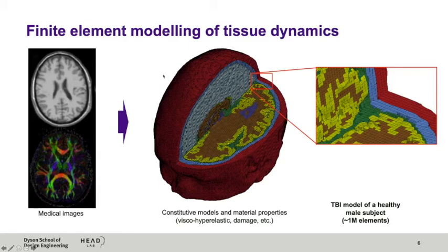And then we represented every voxel of these volumetric images with these cubes. You can see squares here, but in 3D you can imagine it's a cube. These cubes are called finite elements, and basically they define the geometry of different tissues with quite high fidelity. You can see the grooves, the wrinkles on the surface of the brain, as well as different tissues. Once we have this geometrical definition of the anatomy, we define the relationship between force and displacement. And this is done by using constitutive models.